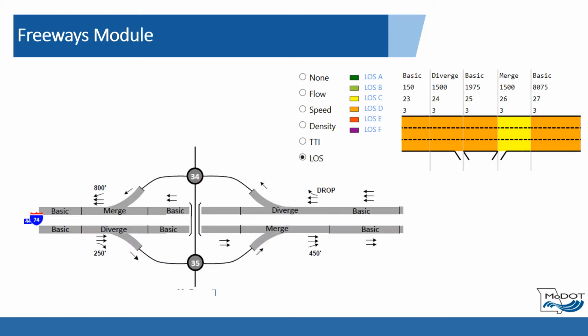As a deterministic analysis software, the Freeways module can quickly provide analysis results with minimal data requirements, making it one of the more applicable HCS modules with the ability to efficiently evaluate multiple scenarios during the alternatives analysis. Particularly, since the other freeway analysis software option would be a time-intensive, data-heavy simulation tool such as Vissim or Transmodeler.